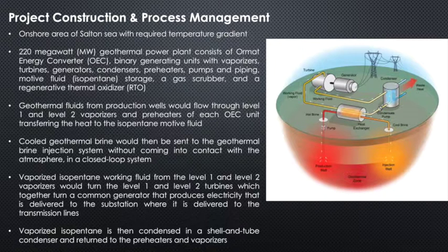The hot water flows under its own pressure from the wells, as you can see these production wells here. As it flows upwards, the pressure decreases and some of the hot water can boil into steam. More steam is produced in the plant by reducing the pressure of the produced fluid in the flash vessel. The steam is then separated from the water and is used to power the turbine generator. So we can see over here the pipes for the working fluid where the steam is separated and used to rotate the blades of the turbine that essentially help us rotate the shaft, thereby generating electricity.